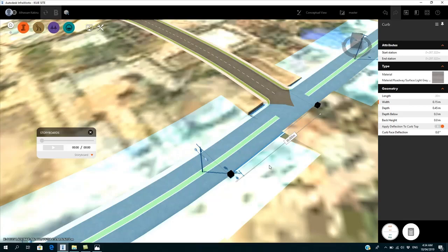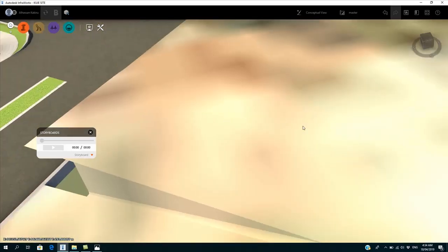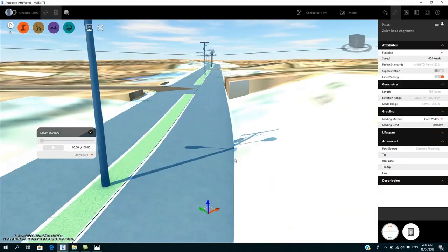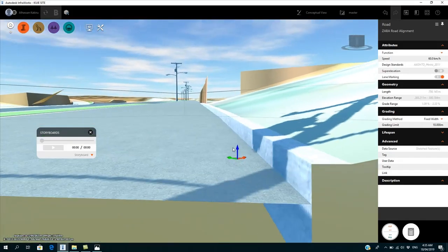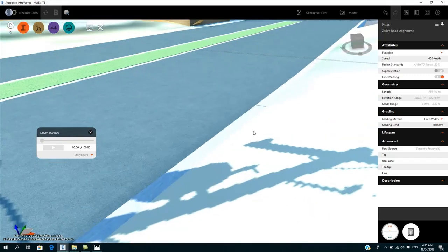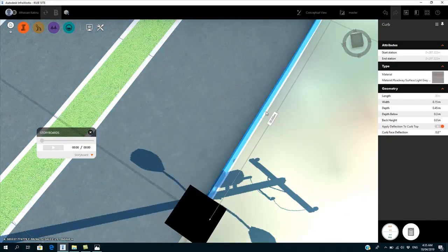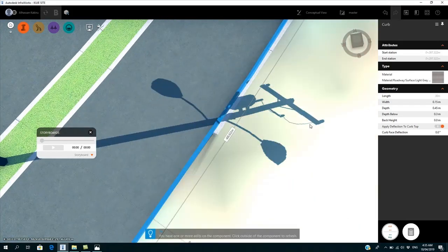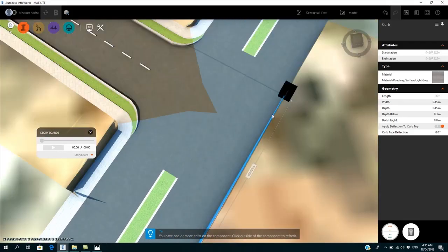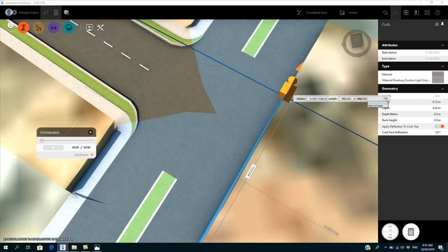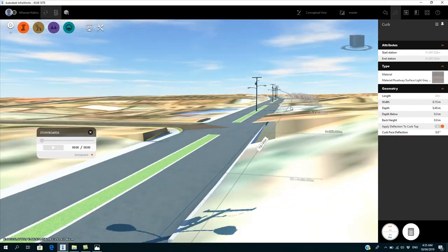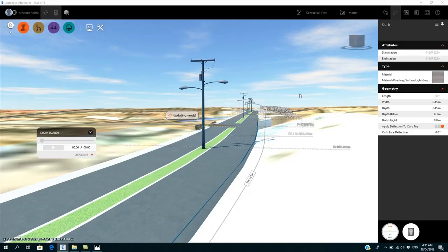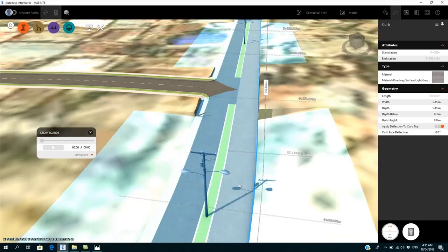Then when you do that, before you extend it, you can check what you have in the provisions. When you click on it, you can see how it's being shown, and look at the curb, you can see 150 as the top of the road. So this needs to extend to the end. We click on it, then you select this, click here. So end of road, then the other one, the beginning, will reflect this to extend to start of road. So complete the curb line, state that. You see? There are other things you need to add here as well. You update it, and the information will update itself as well. So we see it's on the updater.